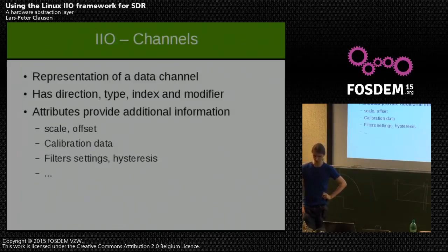But for some legacy stuff like voltage, we use microvolts. And what you don't want to do in your kernel driver is convert each and every sample, especially if you are running at a high sample rate. So we provide a scale and an offset attribute which you can use to convert from the raw sample you have to something in a known unit.